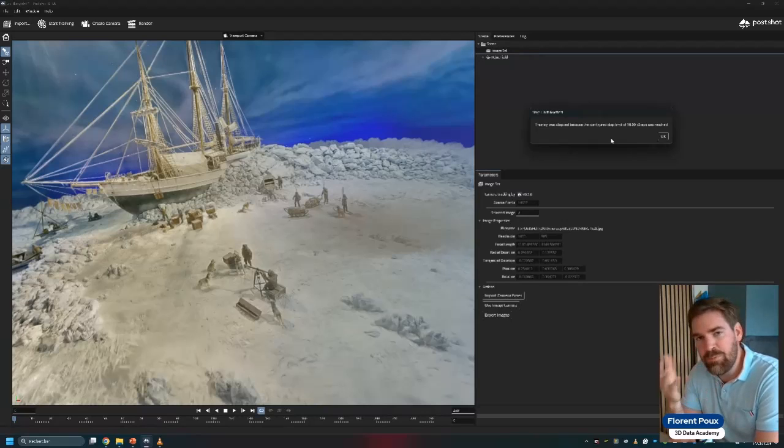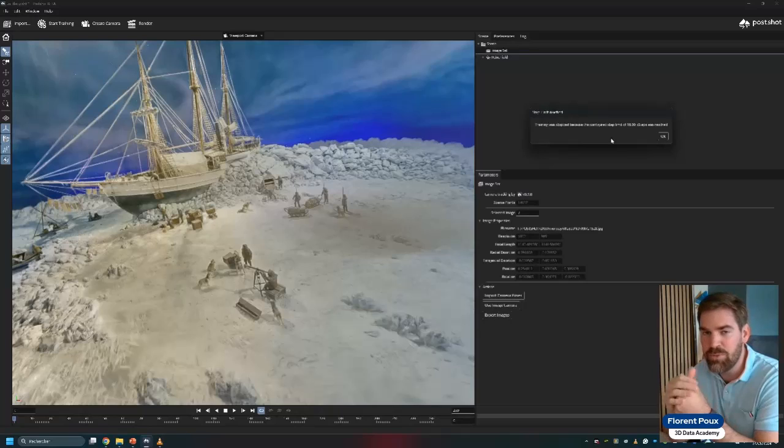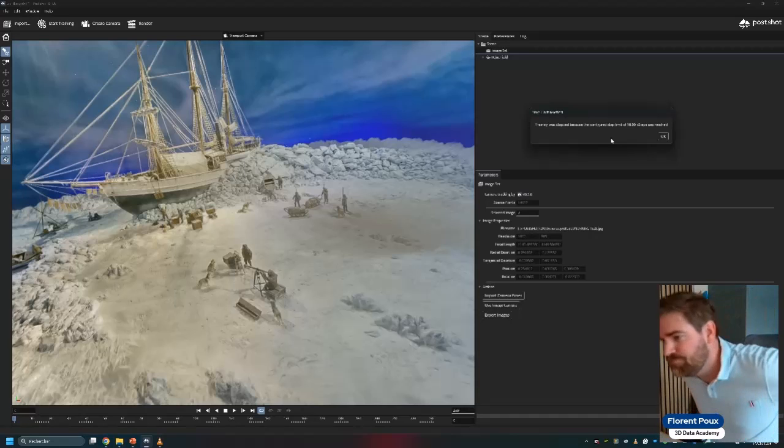But you still need to split your lenses into at least 2 lenses, because otherwise you have too much deformation. The underlying models, usually you will use Brown or fisheye, to model the lens perspective. And this gives much better results if you at least split into 2 lenses, because 360 cameras have at least 2 lenses. If you take the Insta360 X4, the new one, this is perfectly feasible and gives super nice results.